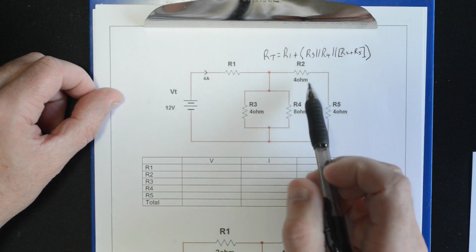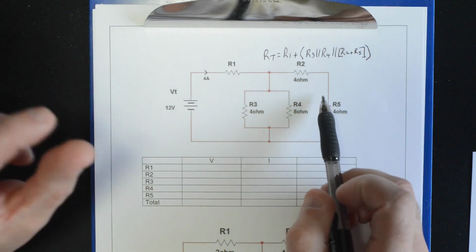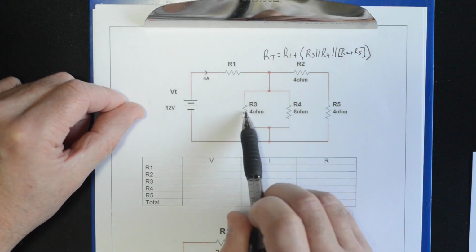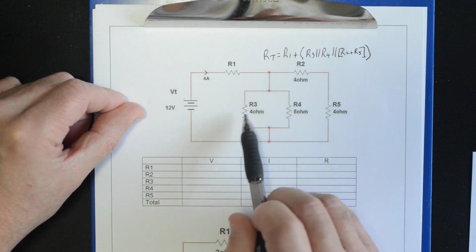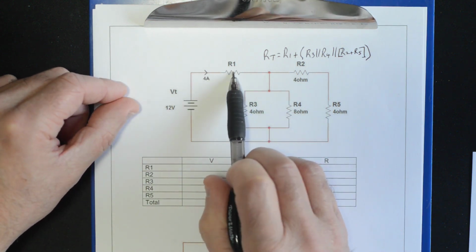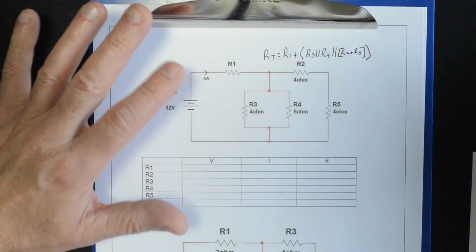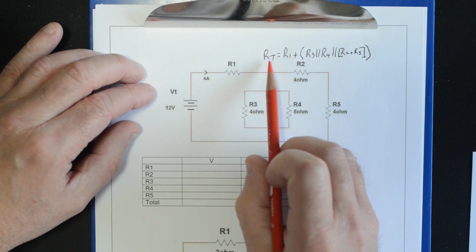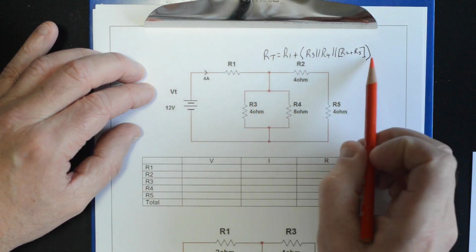That's how we're going to attack these. So we know we have to add these two first, and then that will be an equivalent resistance. That equivalent resistance is in parallel with R4 and R3. You work out the parallel resistance calculation for that, and if we had R1, we would just add it to R1 and we would get RT. That's how we would attack calculating RT, and that's how you want to look at the circuit, because it's laid out just like that.